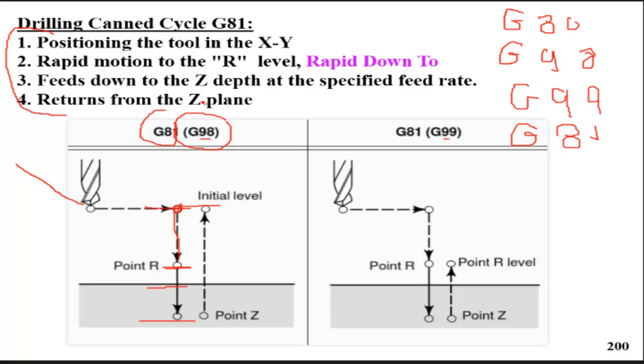How does this line look? This is how it looks. It starts with the canned cycle under consideration, which in our case is G81, and the X, Y and Z. This is to bring the tool to the initial position. This is the function of X, Y, and Z here, of course referring to the zero point or the origin.